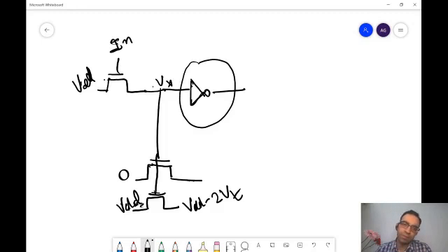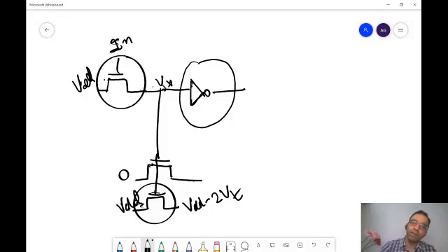Are you able to see this? So why is two coming exactly? One VT drop because of this, and one VT drop had already happened here. For the inverter, we had to implement it statically. So now what do we do? So you see, this doesn't work. You will have to use an inverter there.